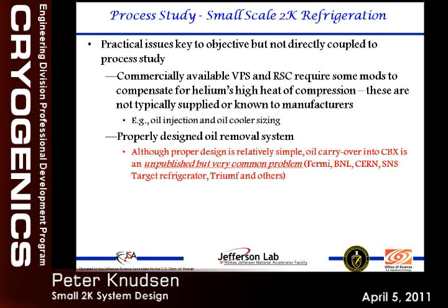Okay, so before we begin, we should look at some practical issues that are important to the objective, but not directly related to the process study. The first one is the vacuum pump systems that you'll typically try and buy commercially. A number of modifications are necessary before you can actually use them. One of them is vacuum pump systems need some extra oil injection help for cooling. You also need a properly designed oil removal system for your positive compressor system.